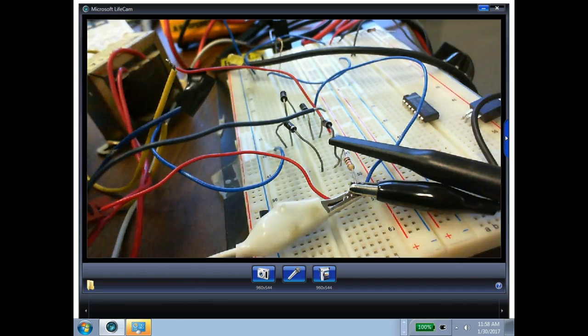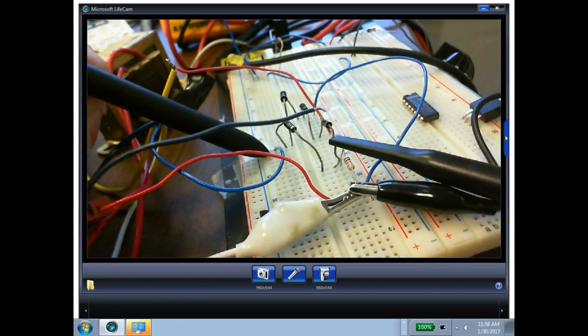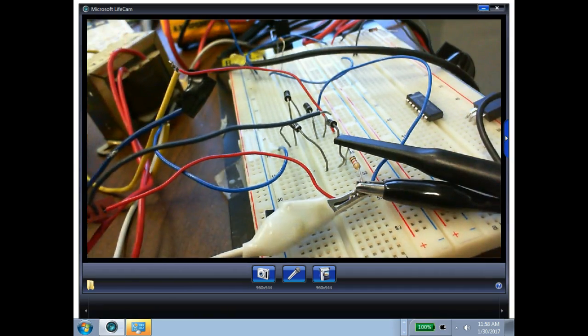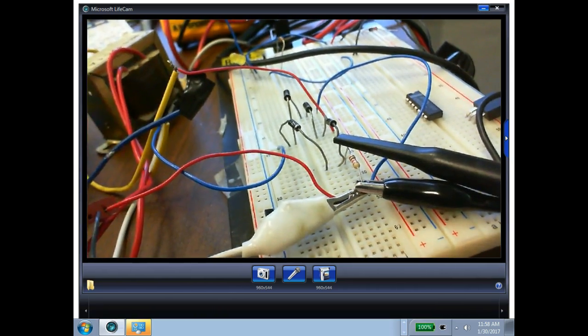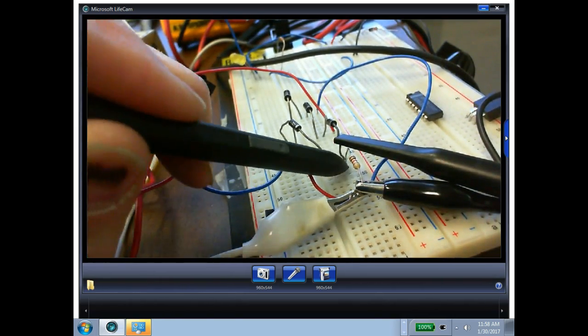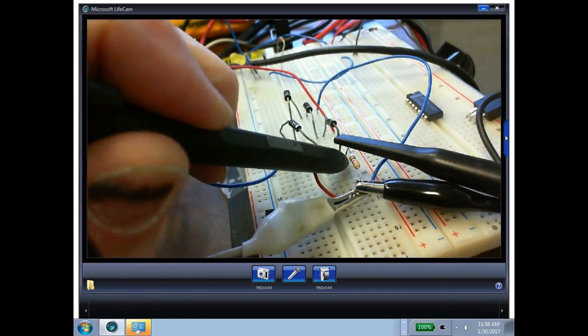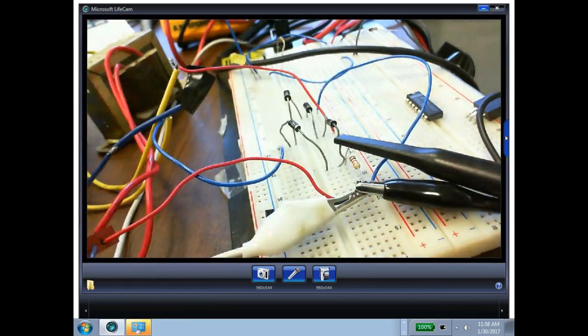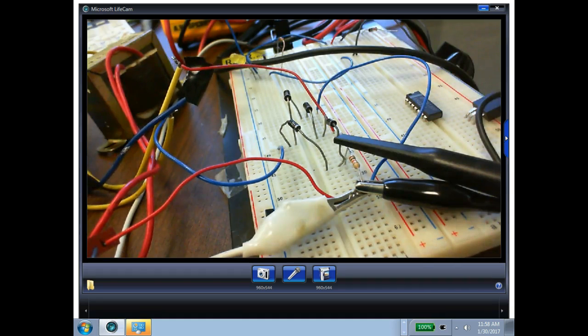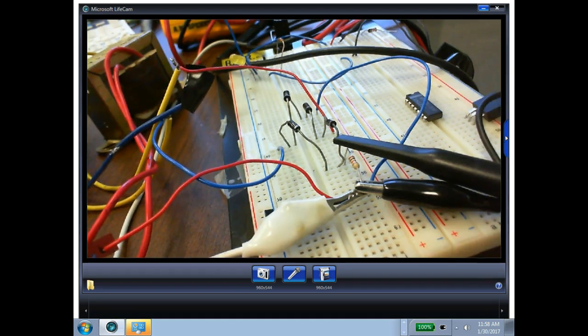I'm bringing in my transformer. One side of my transformer is coming into this anode cathode combination. My other side of my transformer is coming into this anode cathode combination. And here's my load right here connected to the cathodes. Now, the problem is we connect it to the cathodes, and people say, okay, that means it's a negative supply. But what we're trying to do is look what's pointing back toward the source. So the anodes are pointing back toward the source, so this is a positive supply.